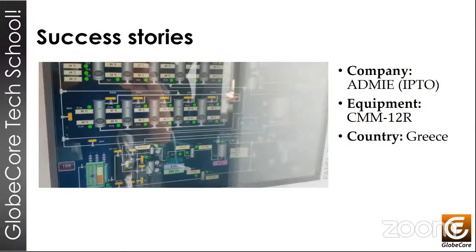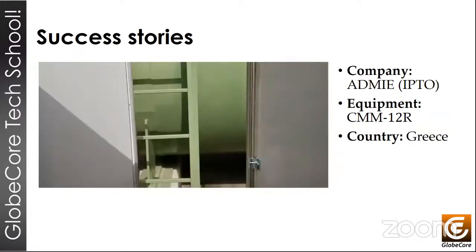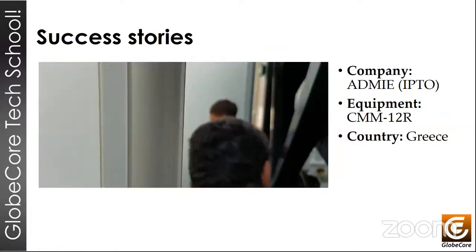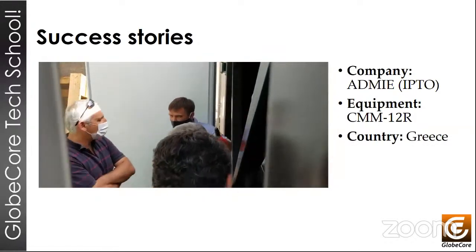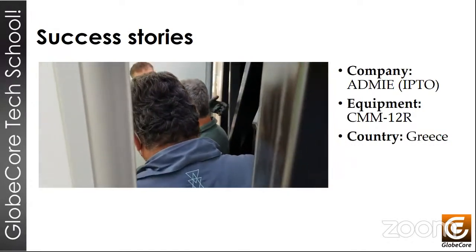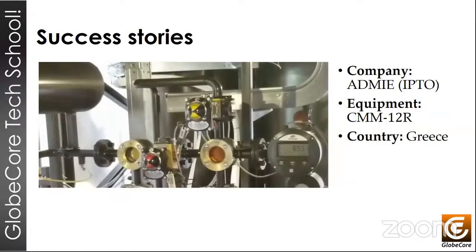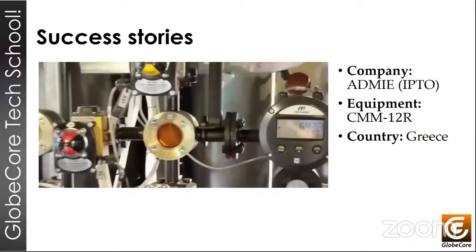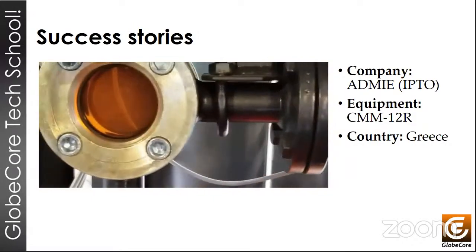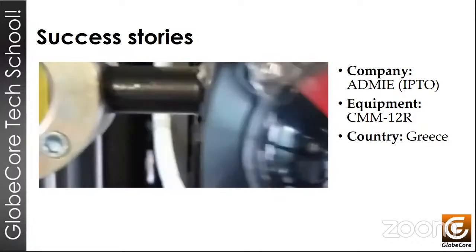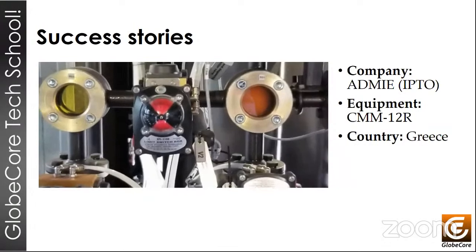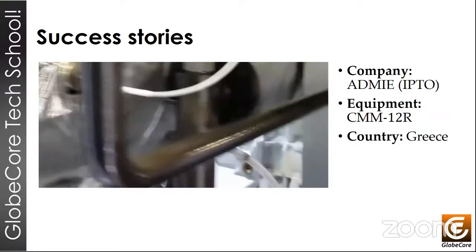The oil was in the amount of 7 tons, and this process was performed in 2 passes through the regeneration columns. Between the 2 passes, the sorbent in the columns was reactivated, and the sorbent reactivation process takes about 15 hours, and in this case, it was automatically managed by the PLC. Here you can see the difference in color of the oil. This is the flow rate, and this is the color of the incoming oil and the color of the outgoing oil on the left. If you do this process in several cycles, you can achieve a very clear color of the oil.